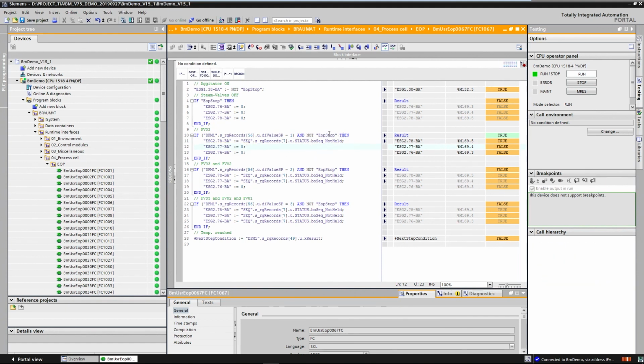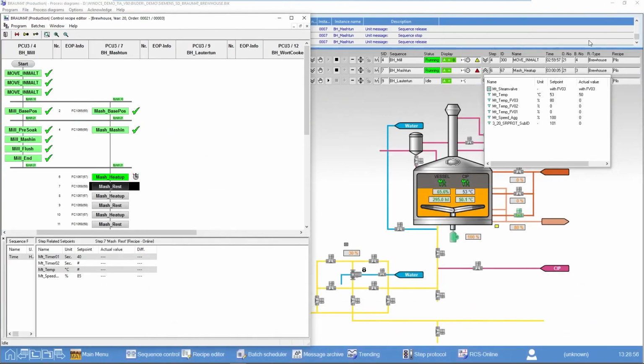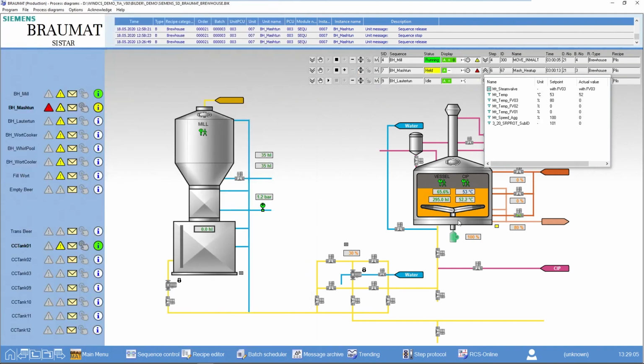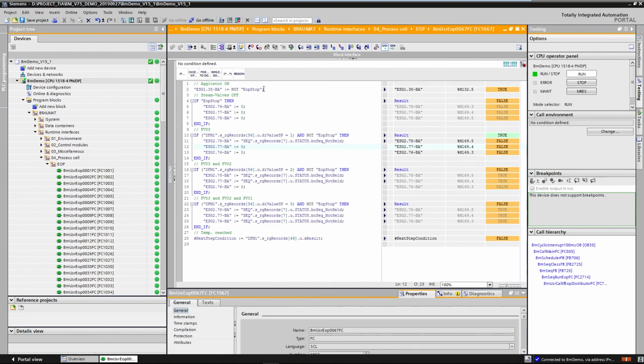Including the connection with an attribute on the unit, namely the hold attribute, we can implement a further interlock here. i.e., always, and now please note the difference, agitator valve, whenever I set the subsystem to hold, the corresponding steam valve is deactivated, but the agitator remains active. That is this command up here. The last command within a step is always the step on condition.